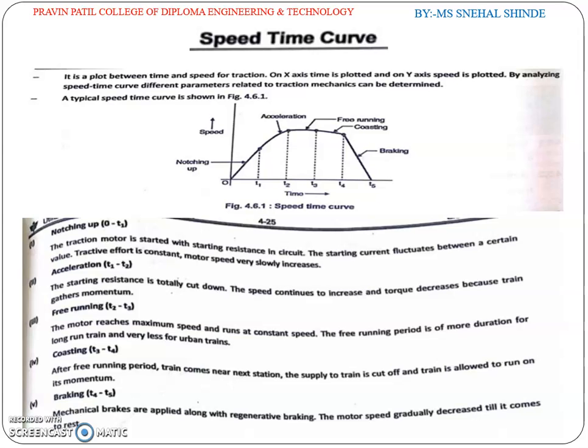The acceleration and the free running periods are governed by the speed torque characteristics of the motors. So this parameter should be available for calculations related to the curve portion T1 to T3.